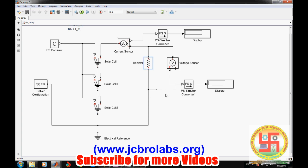First let's make it an open circuit test. Let's see the open circuit voltage of this cell. Yes, the open circuit voltage is 1.8, right? And now let's find the short circuit current. So we have short circuited, in which case the voltage will be 0. And it is showing us 6 milliamperes.